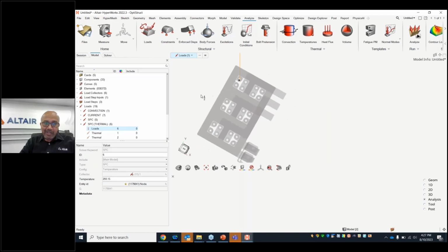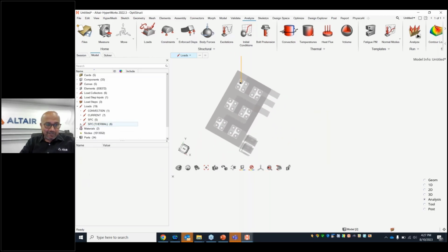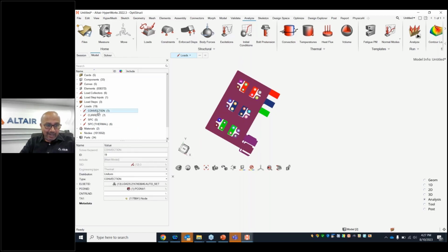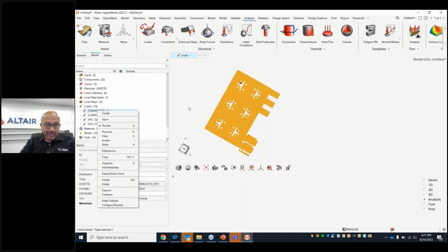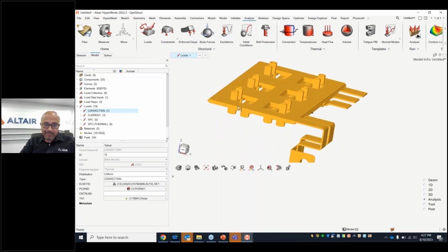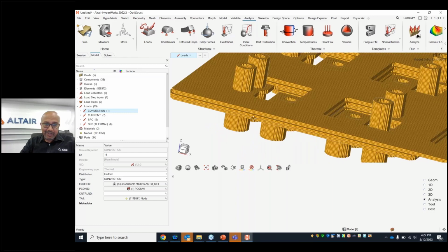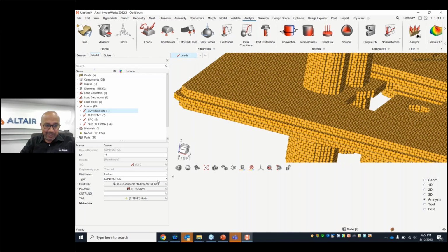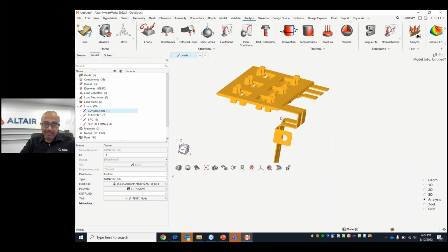For the convection, I have to set up the convection card, and I have created it on all the surface boundaries chosen in my element set, as the faces of these elements, as convecting surfaces.